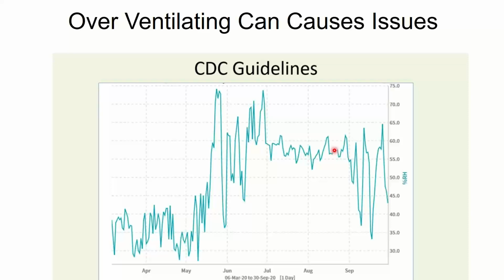because if I'm below 60, I'm obviously below 65. And personally, I like to control spaces, which we'll talk about, to 55% humidity because most of the controls let the humidity float 5%, so it'll float up to 60, and then my system will drive it back down to 55. And then the sensor will let it float up to 60, and I'll drive it back down to 55. So my control set point ends up being 55 in a lot of cases. Or if you've been to any of my residential smart thermostat classes or anything like that, you'll know that I control to 54%.